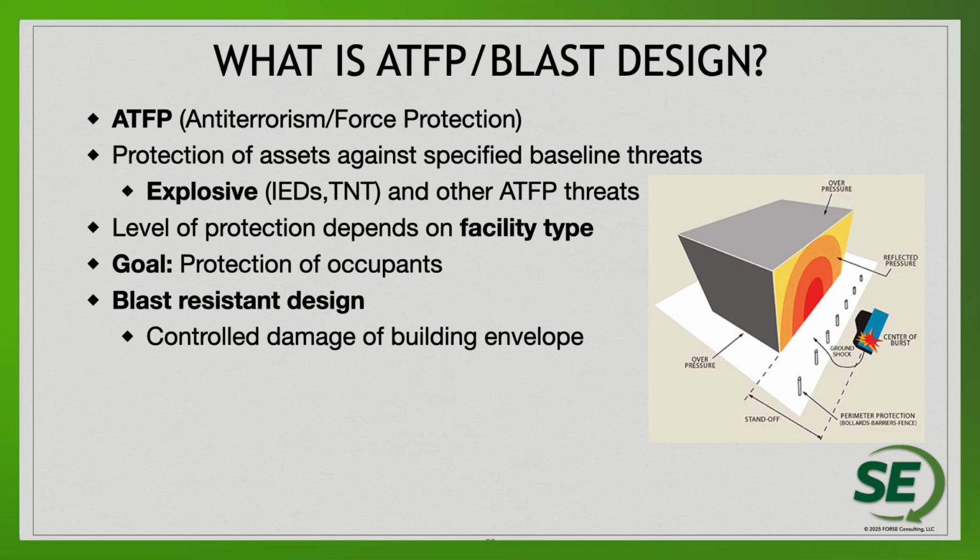The diagram on the right shows the pressure field around an explosion. So you can see the incident pressure, reflected pressure, and the standoff distance. The reflected zone here is really what drives that critical load on a masonry wall.